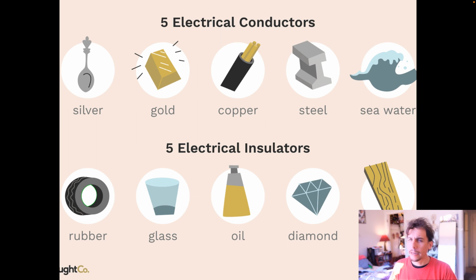Dry wood is an insulator. I kind of alluded to this earlier. Most wood isn't dry though. The wood in a live tree is conductive, and trees do generate a certain amount of electrical energy in them to conduct their bodily functions, and in some cases actually communicate with other trees. Wood that's been rained on, that's absorbed a certain amount of moisture, is going to be conductive because of the water going through it, which is a little bit odd because pure water is non-conductive, but dry wood is non-conductive and wet wood is conductive.